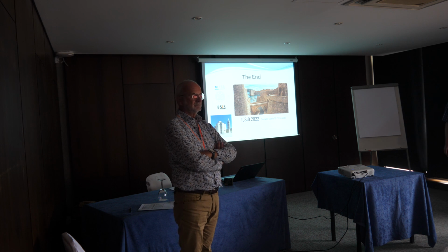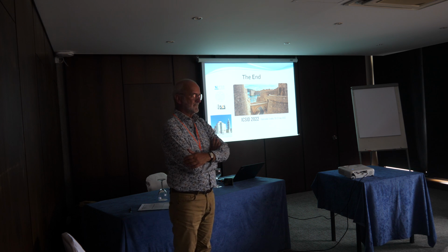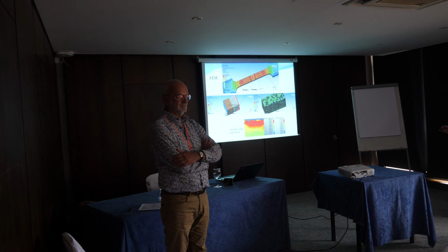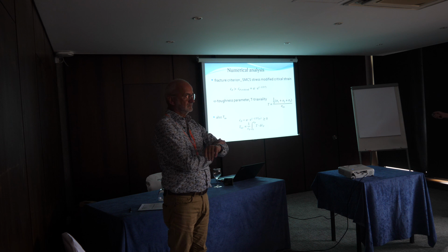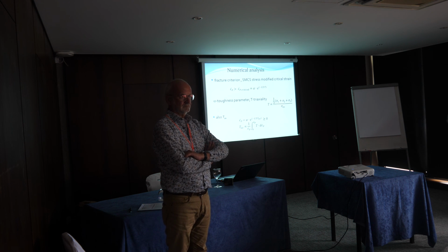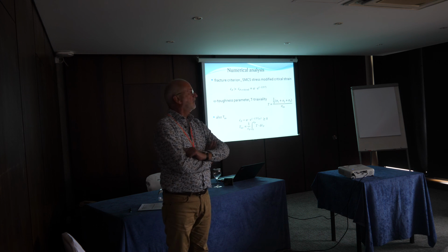Further questions? You mentioned ductile crack initiation. Which kind of criteria did you use? SMCS. Okay. This one, stress modified critical strain. It's easy to employ in finite element programs. Further questions? Okay, then thank you again.